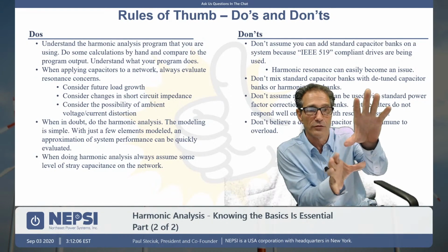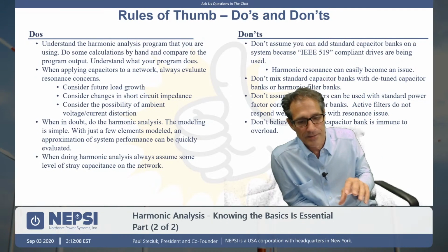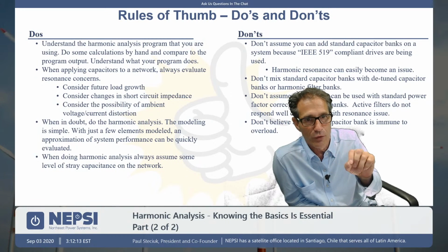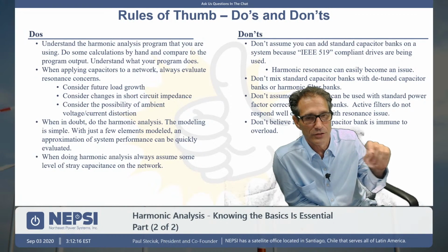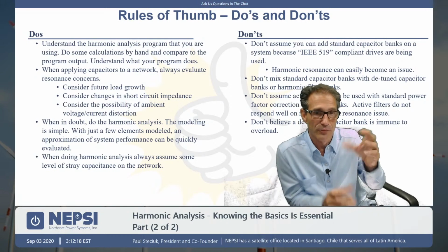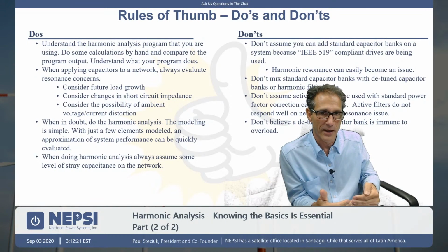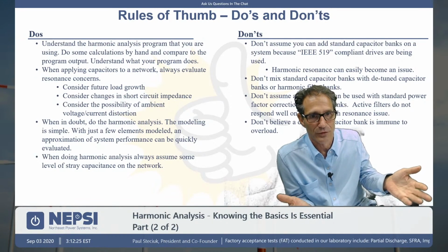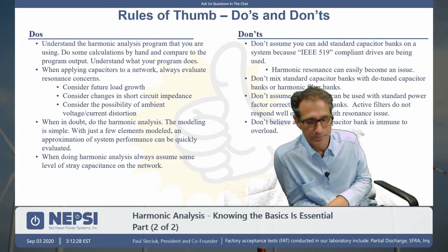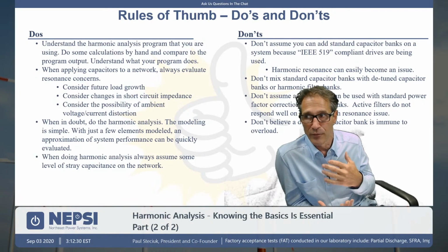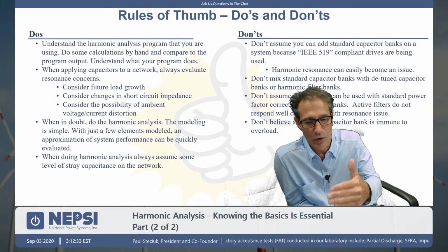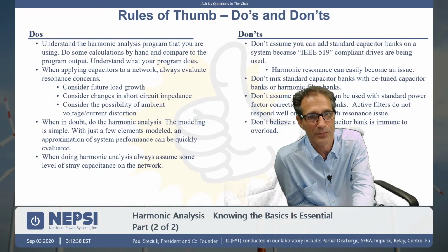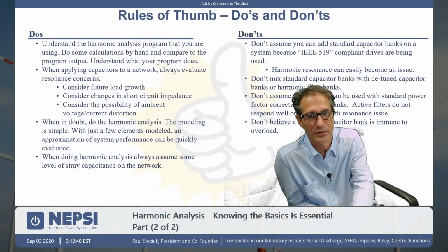So remember, most of the voltage is dropped across the capacitor, so the reactor will only have roughly 1 over the tuning point squared times the line-to-neutral voltage dropped across it. If you bring the reactor to the load side of the capacitor, you have less voltage at that point line to ground, so theoretically you can go with less insulation on the reactor. But from our standpoint, in our designs, not always, I would say 98% of the time, we put the transient inrush reactors on the line side.